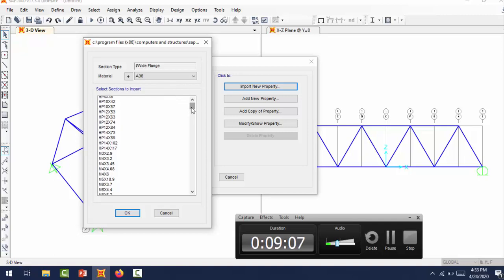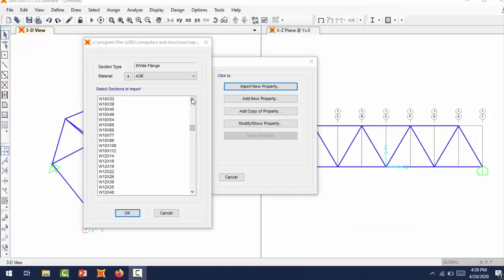Okay, now, as we mentioned at the beginning, we assume that the cross section here is 20-inch square. From the list here, you can pick the cross-section area that you will use. You can pick multiple cross-section areas, but for now, we're going to start with the one that we assume will be used for our primary model, which is the 20-inch square. So 20-inch square, it's W10x68.